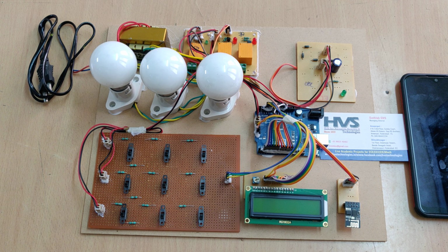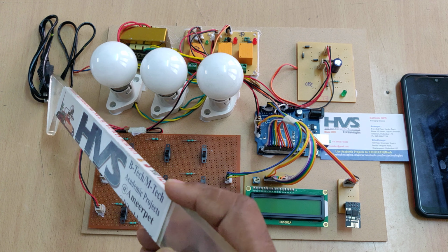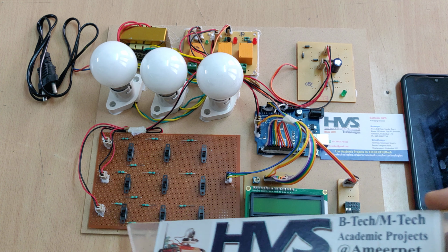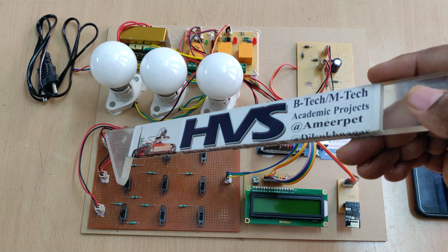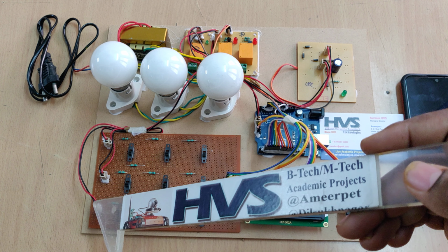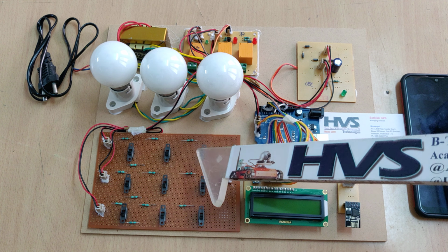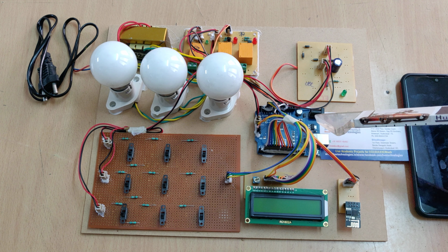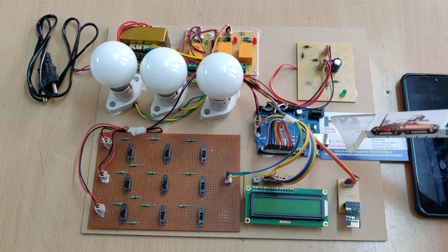through the ESP8266 Wi-Fi module. Here the power flow is: we provide the 230 volts input. In real time, this circuit will take the input of 220 volts from each phase, and that will be converted into DC in order to be measured by our microcontroller, as it works with a maximum of 5 volts.